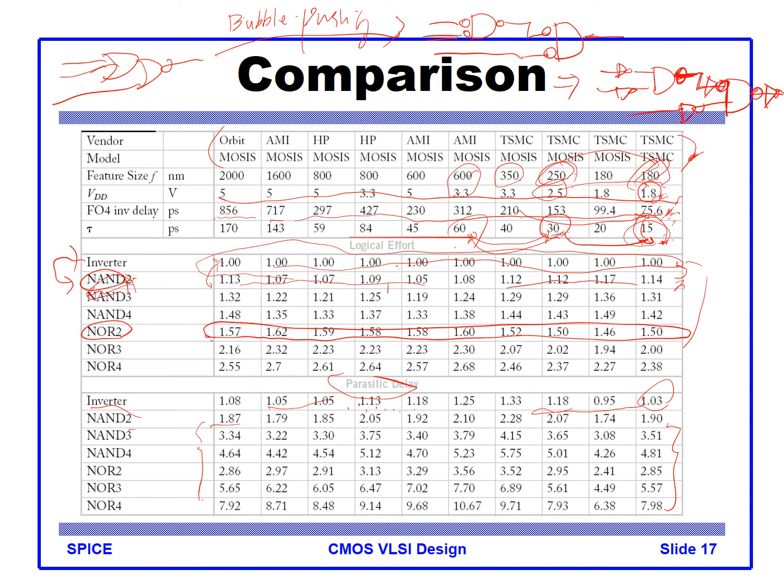You can always transform the logic with NAND gates and inverters, so it is useful to construct any logic you want. Even the inverter can be constructed with the NAND gate. If you are lazy and don't want to design anything, you just tie the NAND inputs together, and that is equivalent to an inverter.